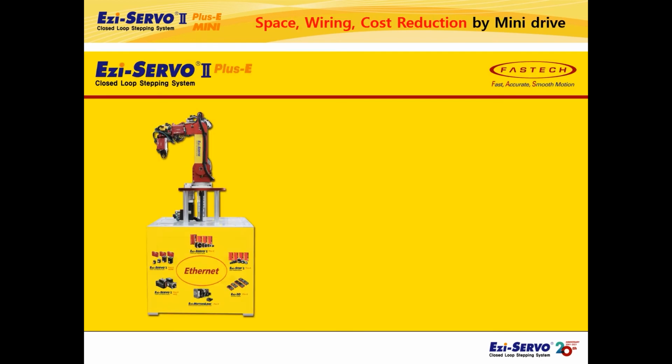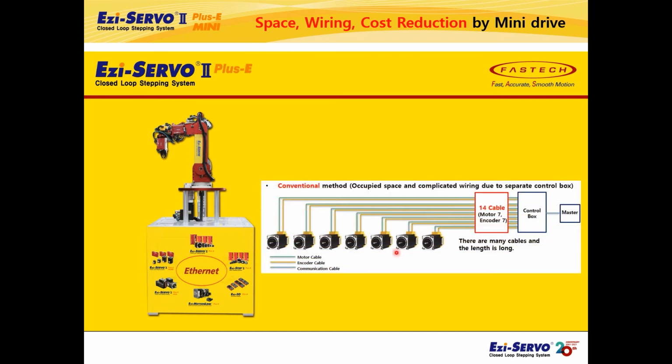First, to explain space savings, wiring savings, and cost reduction, I will show you a 7-axis robot as an example. In general, to operate 7 motors installed to a robot, 7 motor cables, 7 encoder cables are needed. There were a lot of wires because a total of 14 cables had to be connected to the drive installed in the control box.